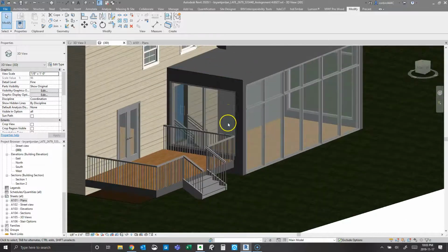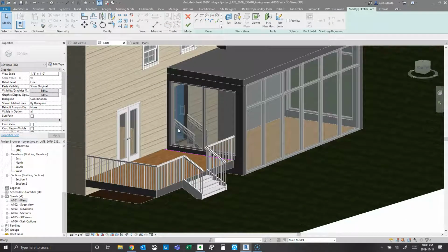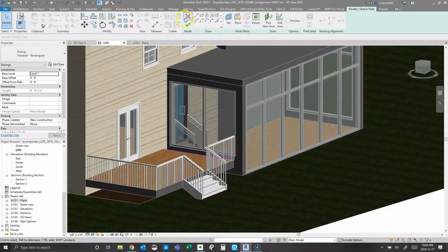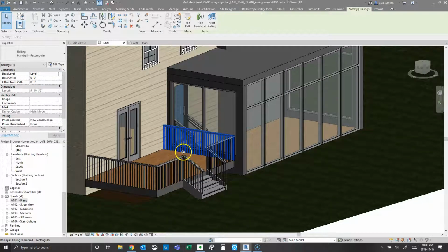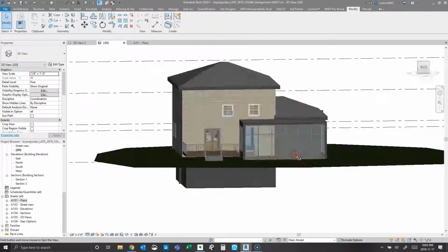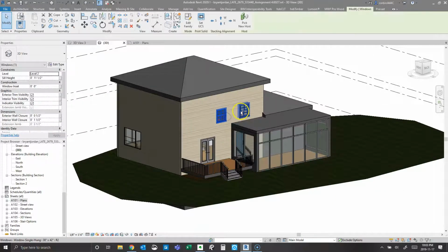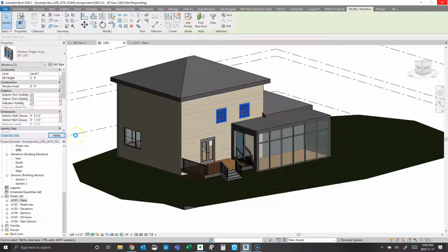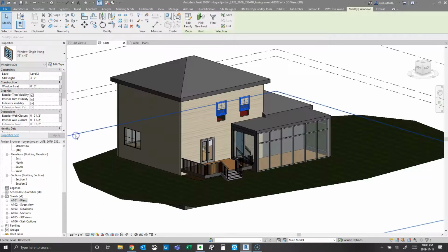So like that, and in that case, we don't need that railing there because it's right up next to that wall. So we can remove that railing. And these windows are very low. So typically when we want a sill height of a window that's a 38 by 42, you want them to be 3 feet high. You basically want the top of the window to be somewhere around 6'8" to 7 feet.